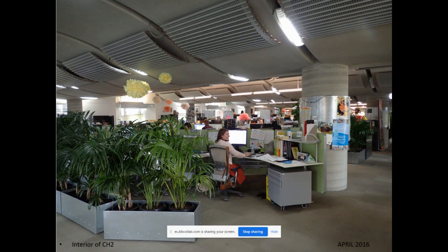So we're not using air for cooling. Air is used for breathing. What we are cooling by is radiance. The ceiling absorbs people's heat, and the concrete ceiling does between 10 and 20% of the heat load, and the chilled panels do the rest. Chilled panels just have cold water, about 15 degrees, circulating through them.